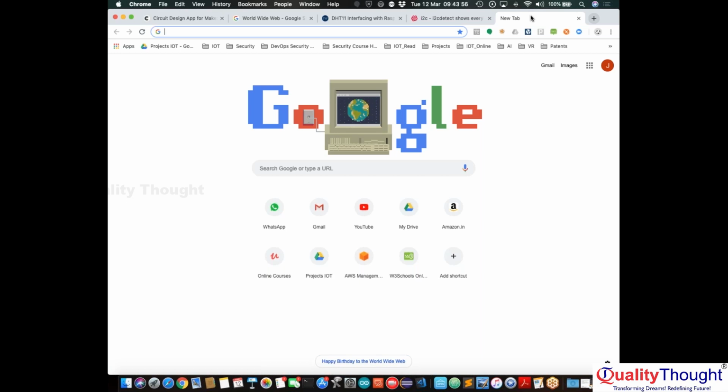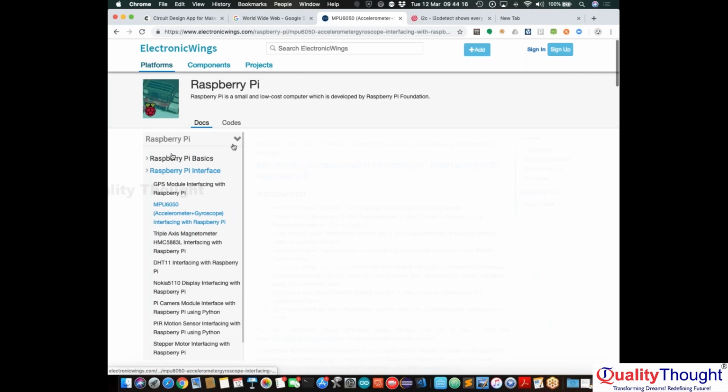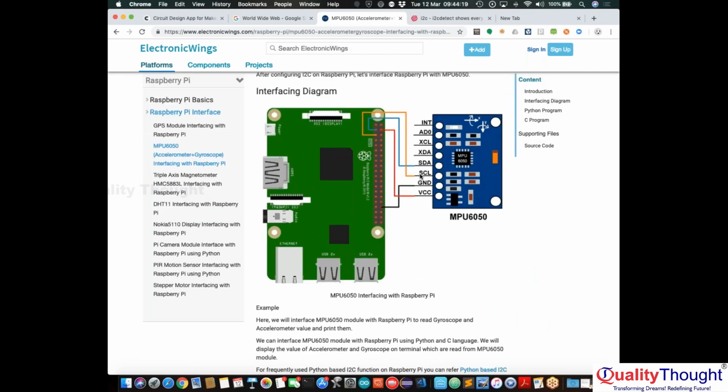Through I2C, you can talk to another chip. That other chip is nothing but an Arduino, and on the Arduino we are going to control the wheels. Got it? Similar to how we have done it here, let me show you that. In MPU6050 you have connected SCL and SDA, right? The same thing can be connected here. Instead of this sensor, I can connect my Arduino board, and that Arduino board will do the actions for you.